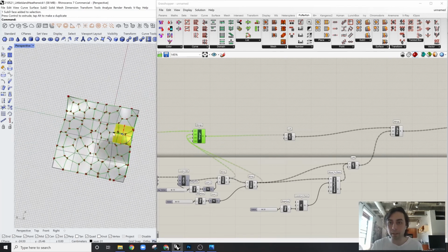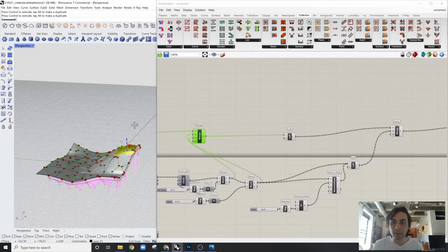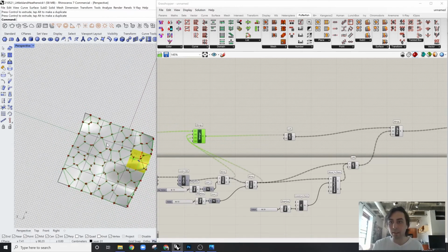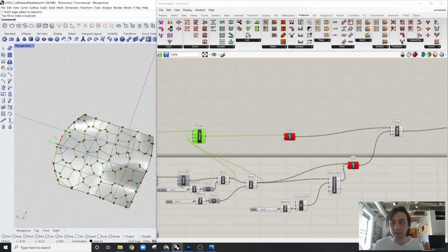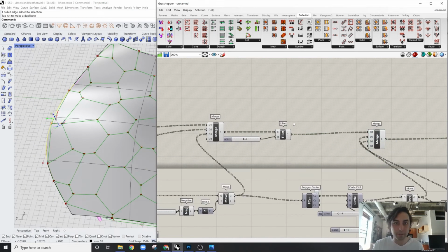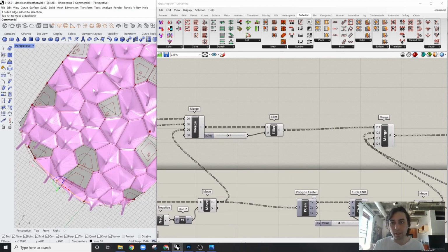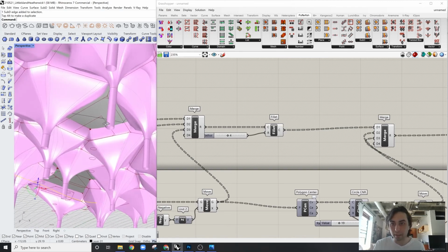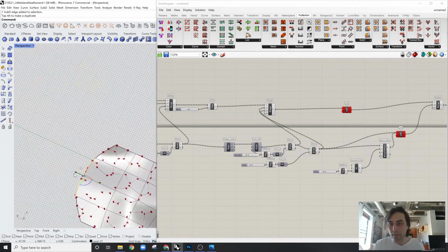But wait, is it because I moved it out of the bounding box? No, I think it was just an anomaly. Let's push it. Let's really see. Yeah, it's not liking that. I wonder if it's because of the fillet. Get rid of the fillet. No, fillet doesn't matter in there. Interesting. So it's making some, but then not others. Crazy.